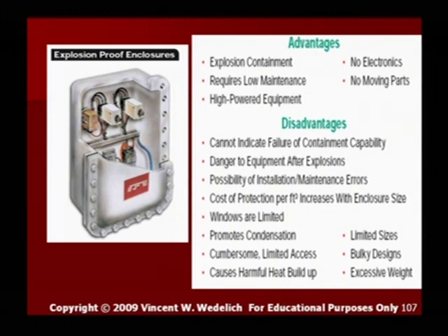The windows are limited. You can actually put windows on these NEMA 7 enclosures, and there's only a limited amount of windows you can install. It does promote condensation because these boxes do breathe. They're very heavy, cumbersome, limited access, causes harmful heat buildup. That's true. Limited sizes, bulky design, and excessive weight. These boxes are heavy. So if you're installing one of these on a skidded application or you're planning on mounting one, make sure you get a structural or mechanical engineer involved to design the supports to hold this box in place, because this is a very, very heavy box.